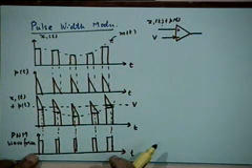Now, the amplitude of this pulse will be constant, because the comparator output just produces a fixed amplitude output of some value, simply depending on whether this voltage is more than this or less than this. That is what a comparator will do, because a comparator has to tell you whether this one is larger or this one is larger, and it does this by generating a voltage value which is either positive, some fixed value, or 0. So, basically the comparator output will be a binary waveform, which is what we have drawn here.